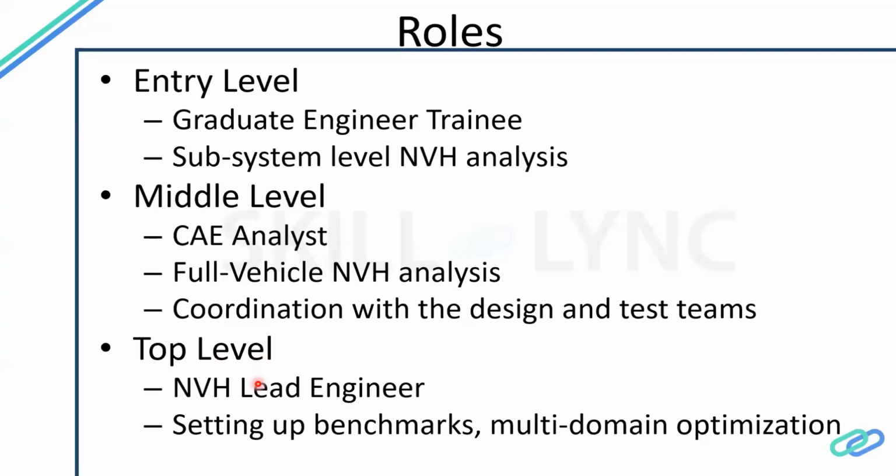Then coming to the top level, NVH lead engineer, you start setting up benchmarks. For example, for any new development project, any new model of a certain company, they will ask you to set the benchmarks for NVH. How much should be the limit for responses in terms of accelerations or forces? That's one of the important tasks.